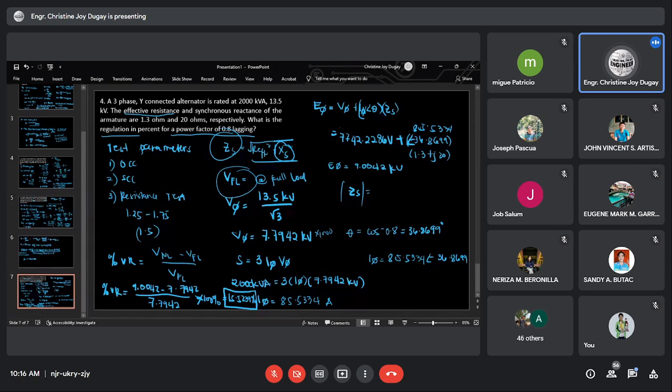But if you do not know the value of, because if you already have the resistance and the reactance, you know the value of Z. Finally, the magnitude is applicable only if you do not know the angle of ZS. Because from R angle of theta, if you have R here, this is already your ZS. Then you can find XS. But since you don't know it, you will apply the Pythagorean theorem here: ZS is equal to the square root of R effective squared plus XS squared. That's how it is.